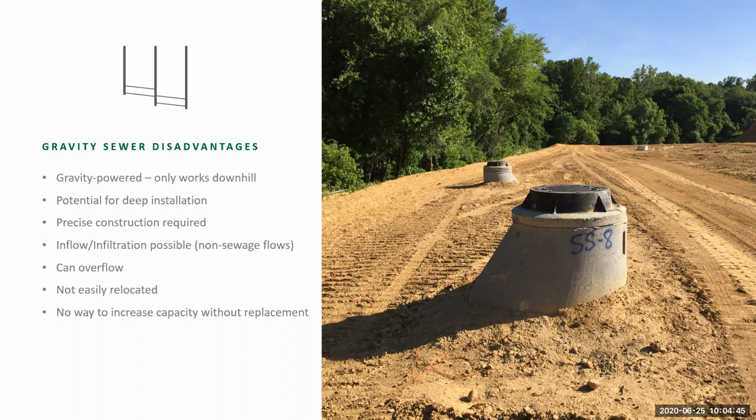The system is open to atmospheric pressure, so that means water, non-sewage flows, can get into the system, inflow and infiltration, so rainwater or groundwater. And if water can get into the system, it means that water can get out of the system. So if there's a blockage or restriction in flow, there's a potential for sanitary overflows.